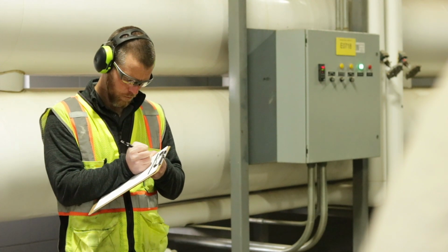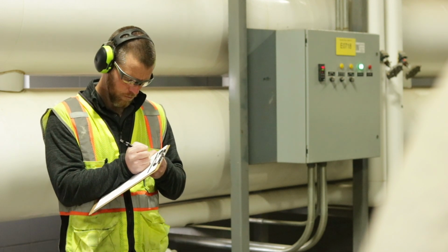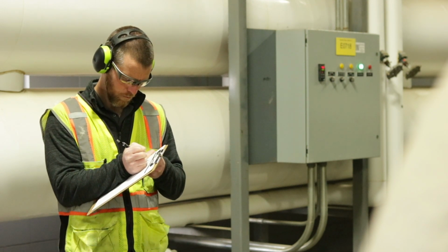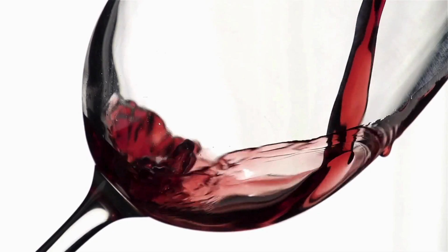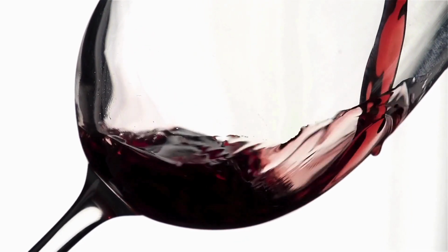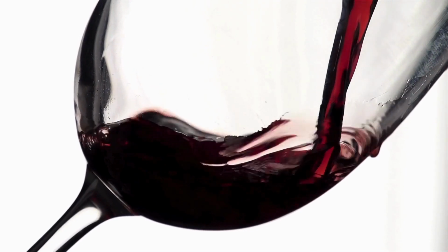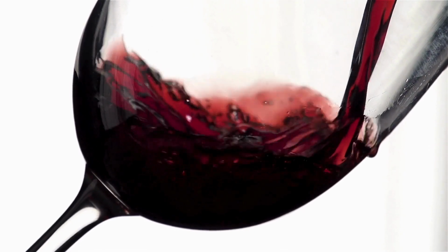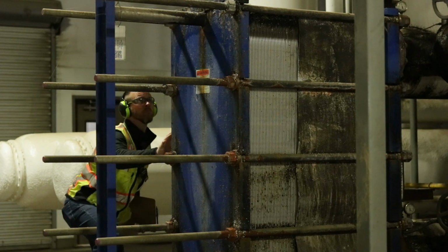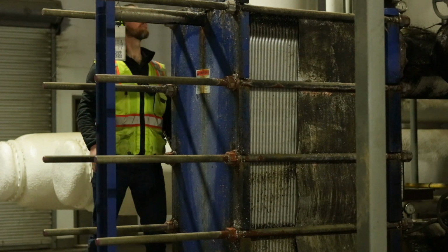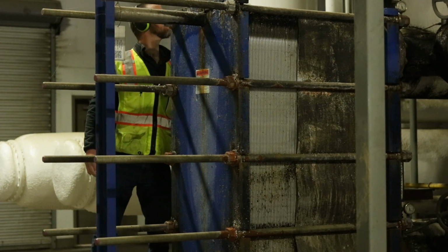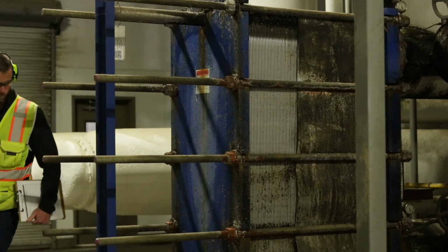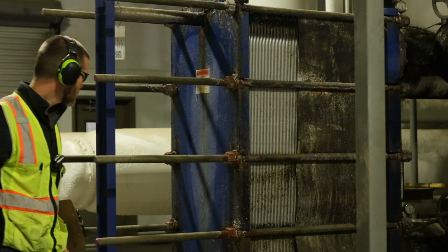Many refrigeration applications employ the direct cooling of a fluid instead of air. Fluid cooling evaporators are used for two primary reasons. First, it is most efficient to directly cool a beverage such as juice or wine compared to using air as a secondary coolant. Second, utilizing a fluid cooling evaporator to chill a secondary coolant such as water or glycol solution reduces the footprint of the refrigeration system.